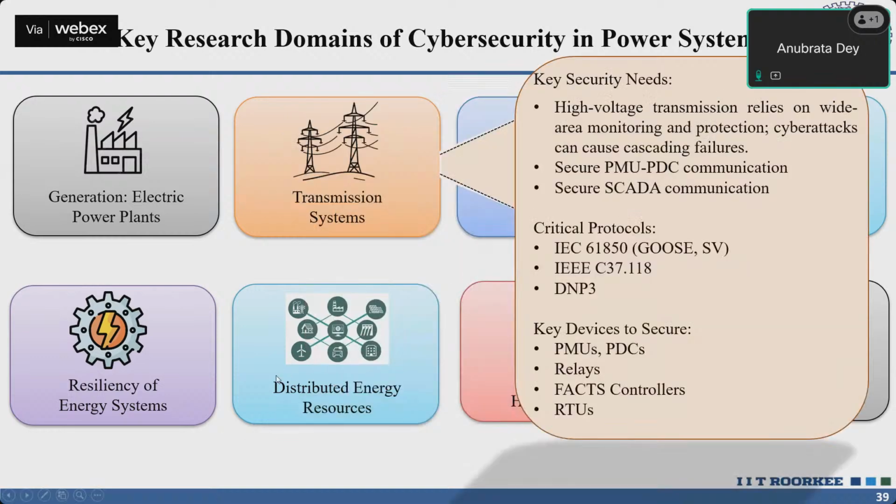The next is the transmission sector. There, when power is generated, the data is transferred by PMUs and IEDs from one end to another end. So there is peer-to-peer communication between PMU and PDC, and secure SCADA communication.